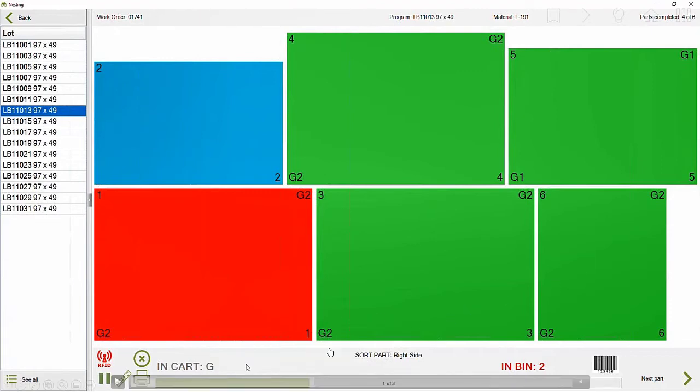If we're printing labels with the Smart Labels, we also identify the orientation of how to place the label. So with the barcode being placed like this, I'm placing the label at 0 degree. But if it's turned to 90 degree, I'm telling the operator that he needs to turn the label at 90 degree. So that helps when you're having a picture with the information of the edge banding, how to edge the part for the edge bander, because the label is oriented in that level.